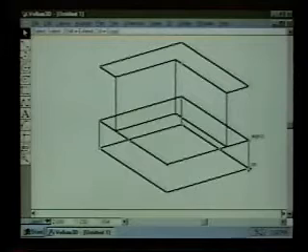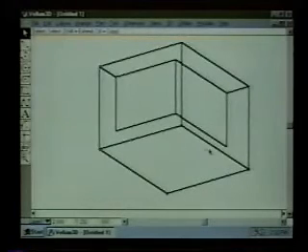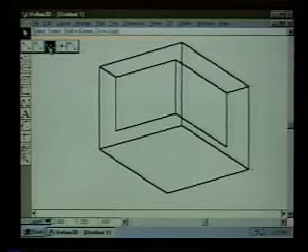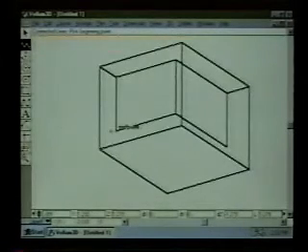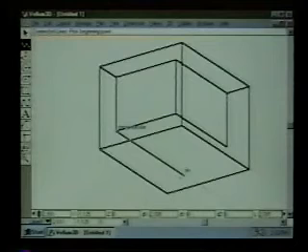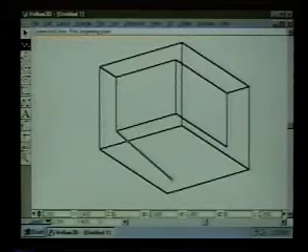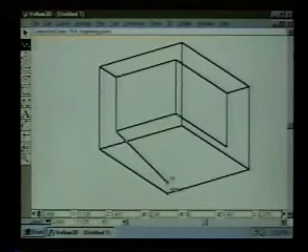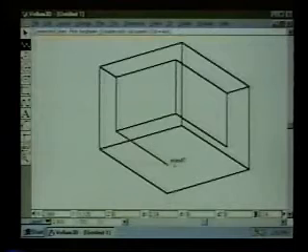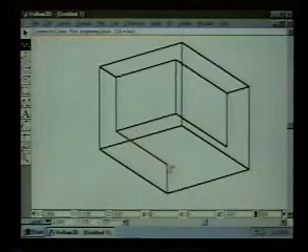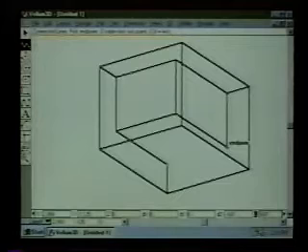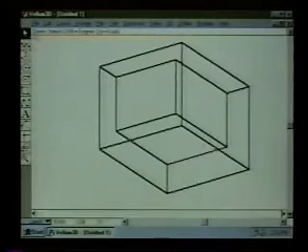Now by doing this, it of course moves the lines that I'm working with, so I need to go in here and grab my connected line tool and put a new line in here. Now again, where is this going to end? Well, the drafting assistant lets me go down for a moment, touch that point to wake it up, and there's the alignment that I need. And then I could go down and finish there, and then I can go from here straight back to that end point.